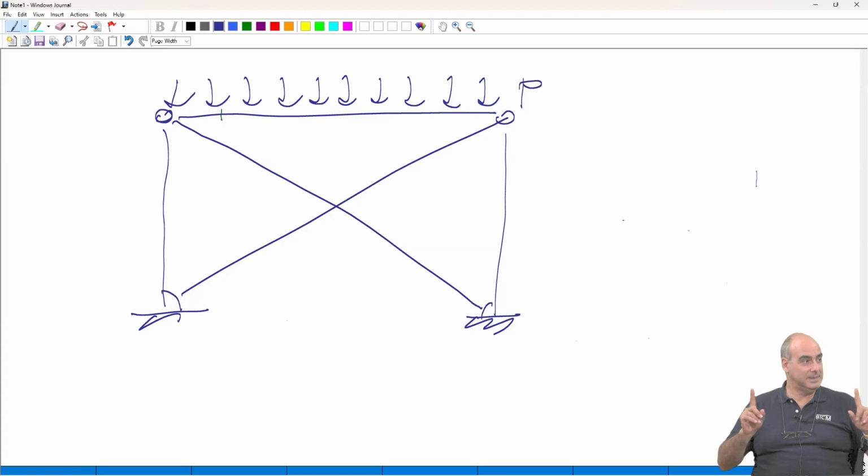But then the cost estimate comes, and this additional cost of the bracing. In this case they are simply two steel ropes. They can be two steel ropes or two very simple L steel profiles. Okay, but you have to provide some steel carpentry plates to anchor them at the column.